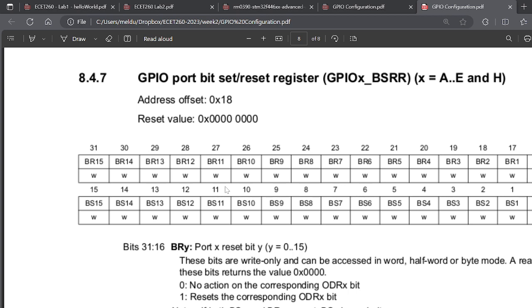And then it's like, okay, any problems with that? Everybody's good with it? So if I write a 32-bit register, if I put a 1 here, I set it. If I put a 1 here, I clear it. Yep. You can write 1s to, for example, both 0 and 16. Yeah. So what happens if you write 1s to all of them? Does it set it or does it clear it? Whatever it does last, potentially.